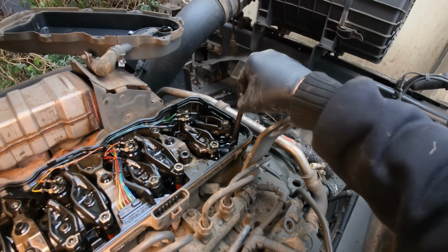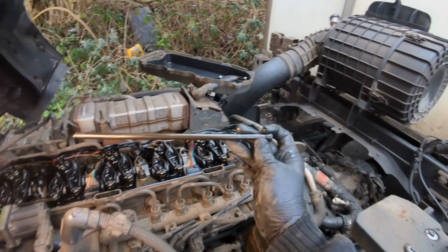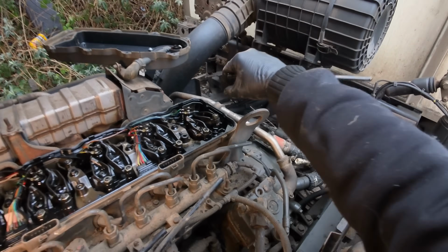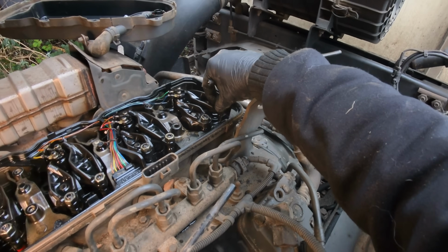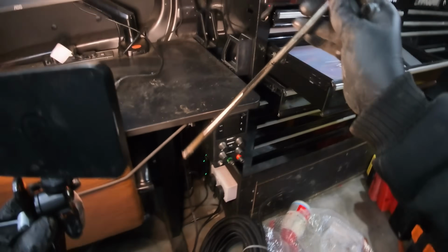Right, is this bent? No. We'll find a straight edge or something flat to put this on and we'll just check it straight. But is it just that this has unadjusted itself and popped out? Hey, that would be amazing, wouldn't it? Right, well, there's no gaps under this push rod. I'd say that's straight. It must have just unadjusted itself.